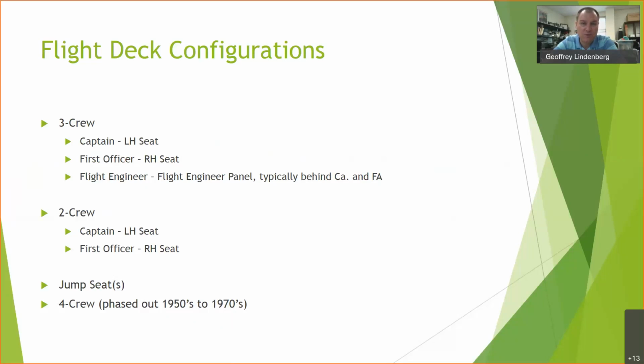Navigation was moved to them as well, and those were also some of the first things that were automated, with what's called an FMS, a flight management system that can interface with the navigation instruments to know where the airplane is and where it needs to go. They interface with autopilots to direct the autopilots, and they can interface with the communications equipment to bring up different radio comm channels and ADF and nav radio tuning and all that stuff. So that was all done and eliminated the 4 crew.